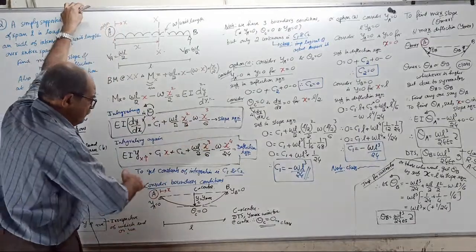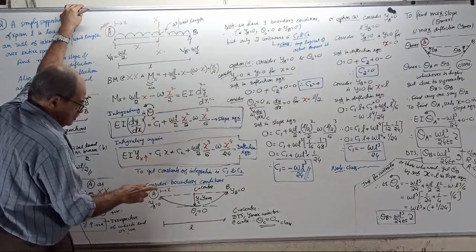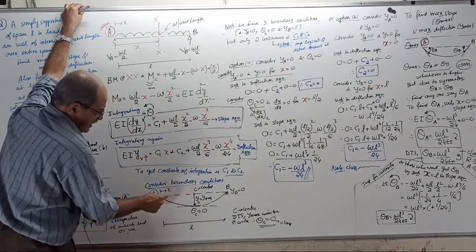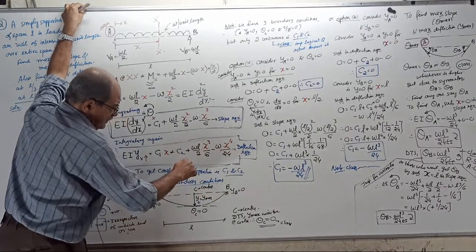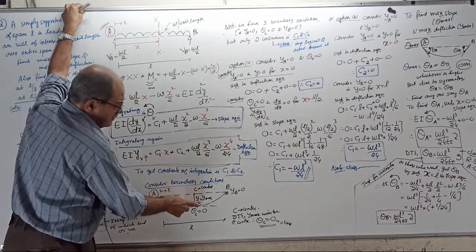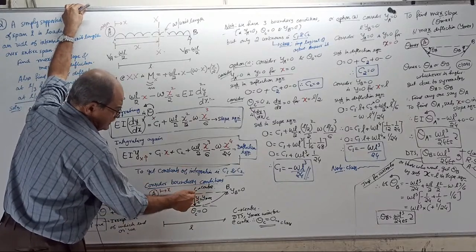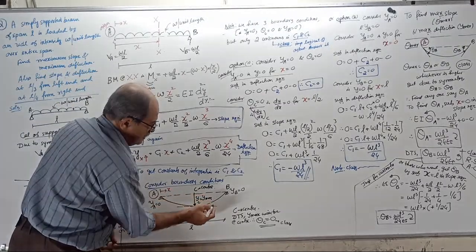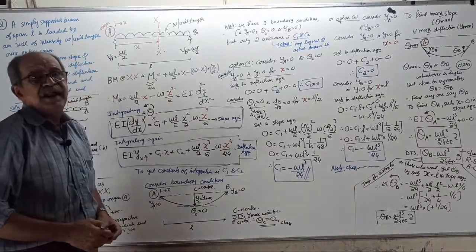So, simply supported beam, see, will bend this way. This is symmetrically loaded. So, whatever is the loading, see, this is called deflection. At A, deflection 0, at B, deflection 0, and also because of perfect symmetry, deflection at C will be maximum. See, deflection at C is maximum.